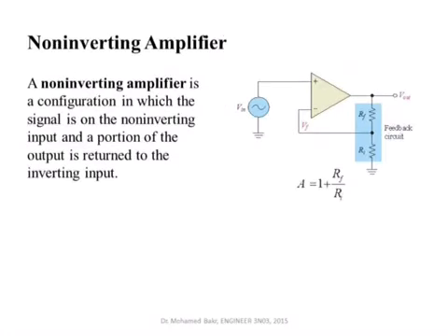One of the most useful amplifier configurations we use is the non-inverting amplifier. For this one we have two resistances, both connected to the negative input of the OpAmp, and then the input signal is applied to the positive terminal of the OpAmp. The analysis of this one is extremely simple and follows the same rules that we applied in our lecture. V plus must be equal to V minus.